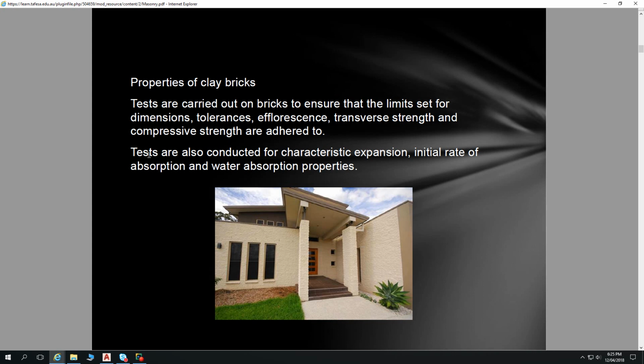Notice the old brick is a bit pre-dimensional standard. So note, you could imagine the difference in the wicking between those two. That old brick is still relatively porous and sandy and has the ability to wick a great deal of moisture, whereas the modern brick is quite well fired and very dense and not so sandy, and is not going to be as porous, and it won't have the same suction on the mortar as the old brick.